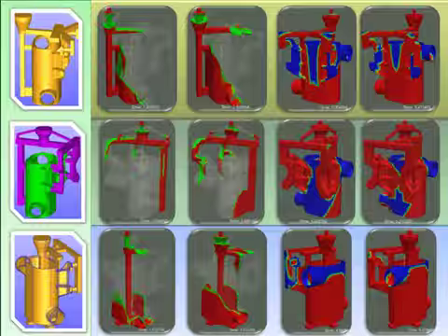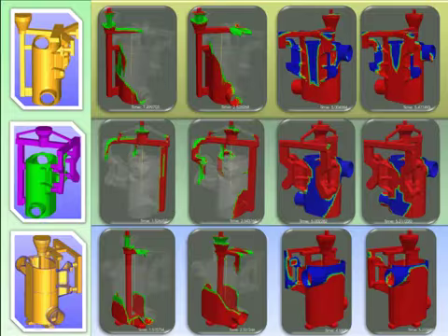The learning curve of Cast Designer is also short. This is an example of Cast Designer CPI for filling simulation. There are 3 design solutions for an investment casting part. The first and second are side filling systems but with different designs, and the last one is a bottom filling system. The red color shows the hot liquid metal, and blue is the air, which is not yet filled. All the metal flow, air entrapment, velocity, vector and pressure can be provided by Cast Designer after the simulation.